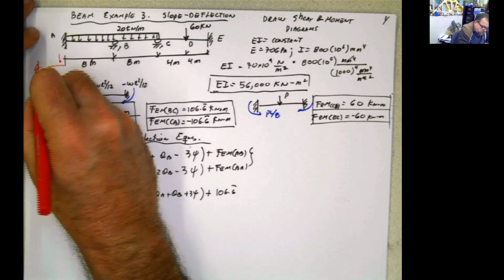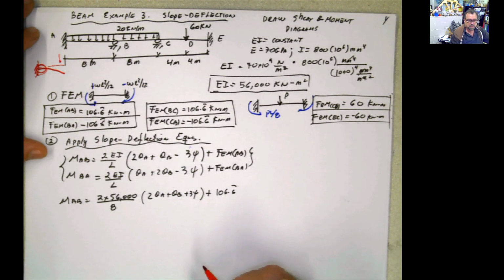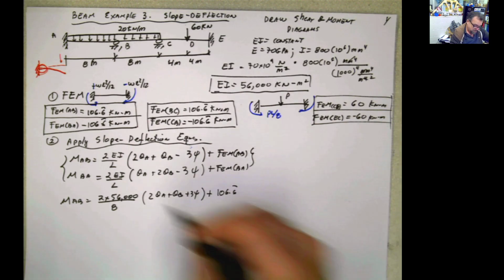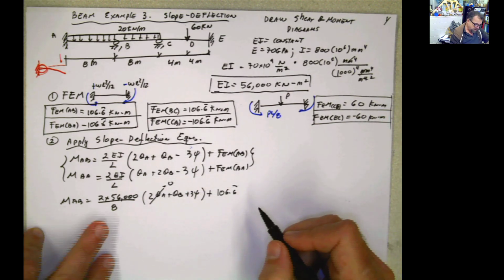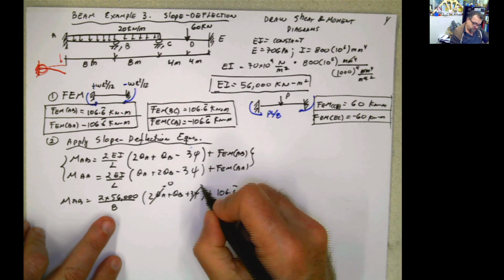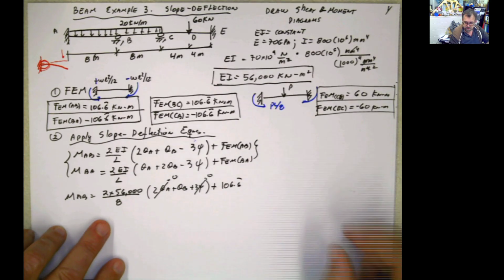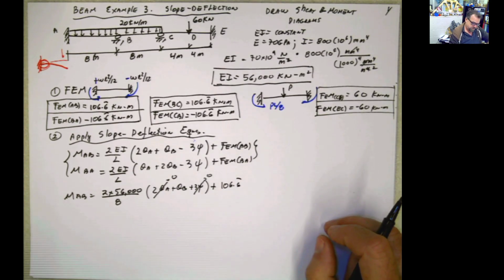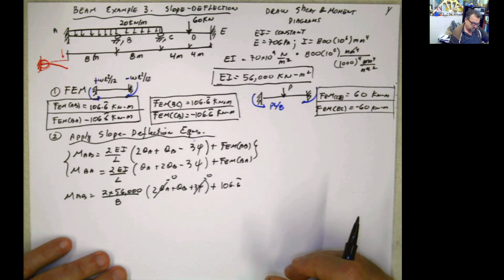If you put a load, the rotation here is going to be 0, as well as the deflection, because it's a fixed support. You're not going to have rotation at that point, meaning this value is going to be 0. And not only that, I already said that this is 0 because there's no differential settlement or relative displacement between the 2 points.